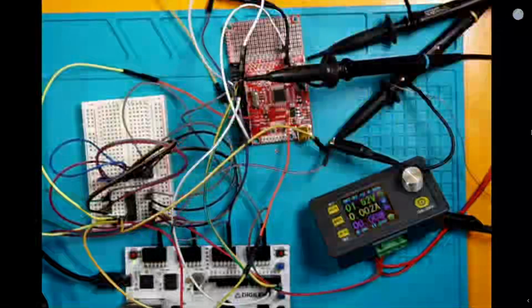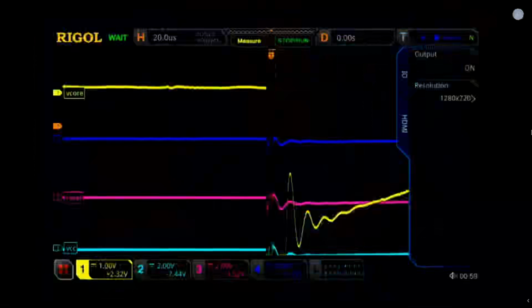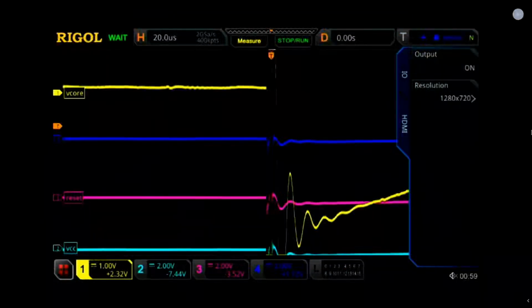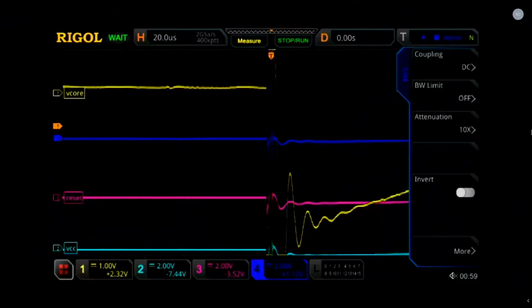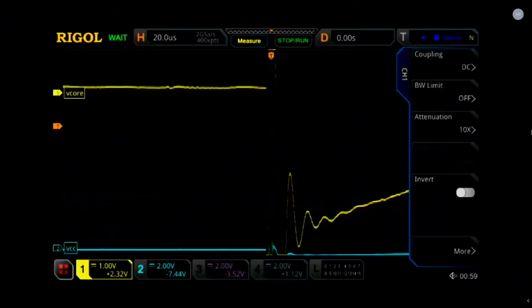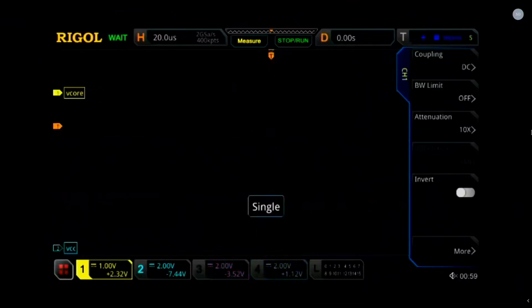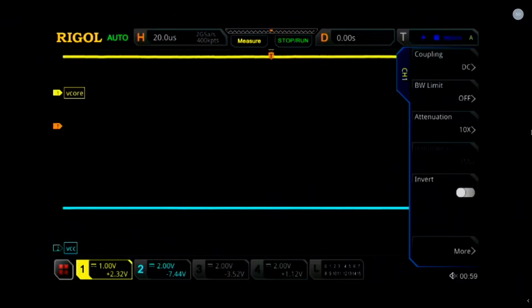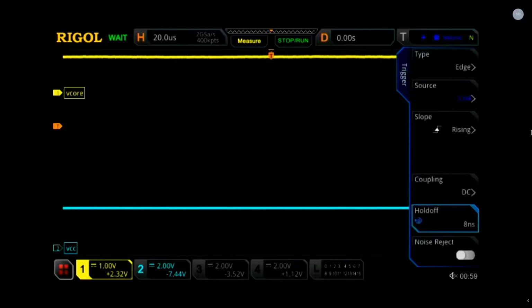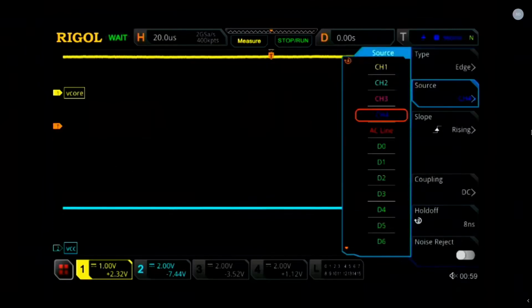So now let's switch to the oscilloscope, and let me actually start the script so that we see stuff. So I'm going to hit Control A X, but I'm just going to start the script. All right, so now let's configure our trigger really quickly. So let's get rid of this guy and this guy because we know there's nothing there. And let's set our mode to auto initially. And let's make sure, let's figure out which channel we're actually triggering on.